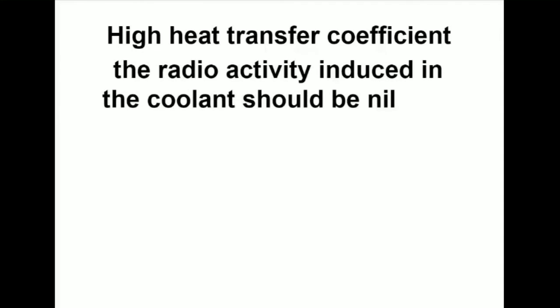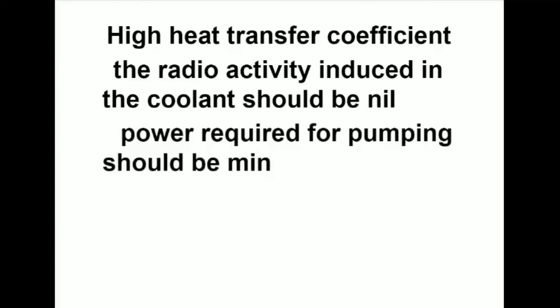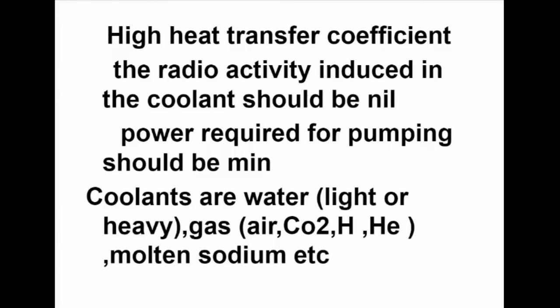Then it should have high heat transfer coefficient. Then the radioactivity induced in the coolant should be nil. The power required for pumping the coolant should be minimum. Then coolants are water, normal water or heavy water, gas like air, carbon dioxide, hydrogen, helium, or molten sodium, molten salt, etc.